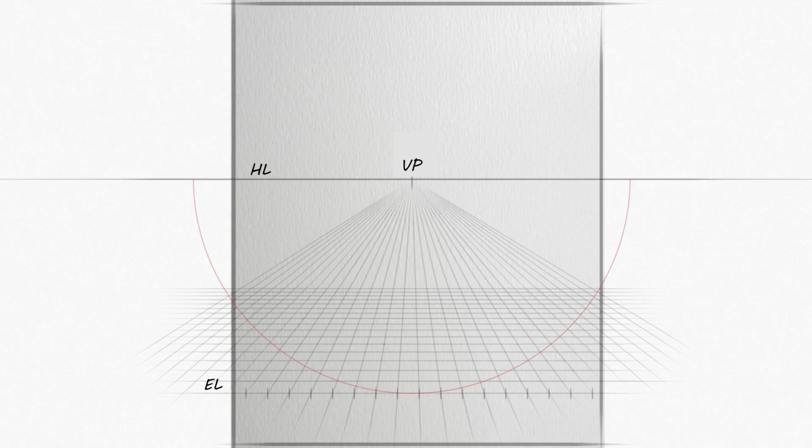To demonstrate how we locate our two required vanishing points, I will first construct a basic square in frontal perspective, followed by a smaller concentric inner square, as shown. By extending the lines of the two closest sides of this newly formed inner figure outward, we successfully locate our two primary targets, vanishing point 1, VP1, and vanishing point 2, VP2. Notice that both of these critical points reside completely outside our primary drawing area.